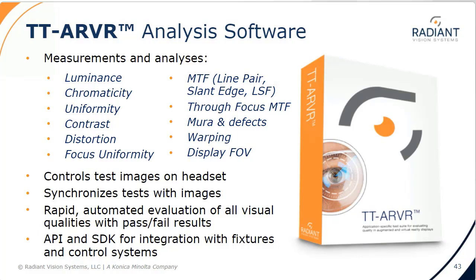The software not only controls the functions of the connected imaging system and XRE lens, but also the test images that are pushed to the XR headset. As an image is shown on the headset, the software initiates a measurement by the imaging system and synchronizes an analysis of the captured image. The software can run the analyses asynchronously, so that allows it to process measurement results at the same time as it's capturing subsequent images in the headset. This pipelines the process and maximizes speed when testing multiple qualities.